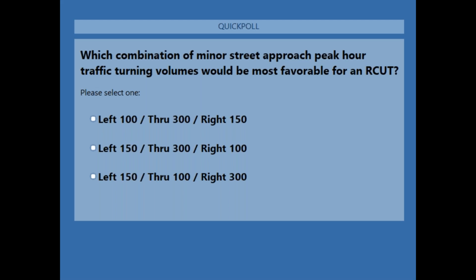Great. We know that there are significant safety benefits of R-CUTs. Are there any crash reduction factors for R-CUTs? Yes, great question. So we are at a point now where we are able to develop crash reduction factors. On the crash modification factor clearinghouse, you'll find some examples of studies in North Carolina where they have a lot of R-CUTs. They have generated a safety evaluation report.